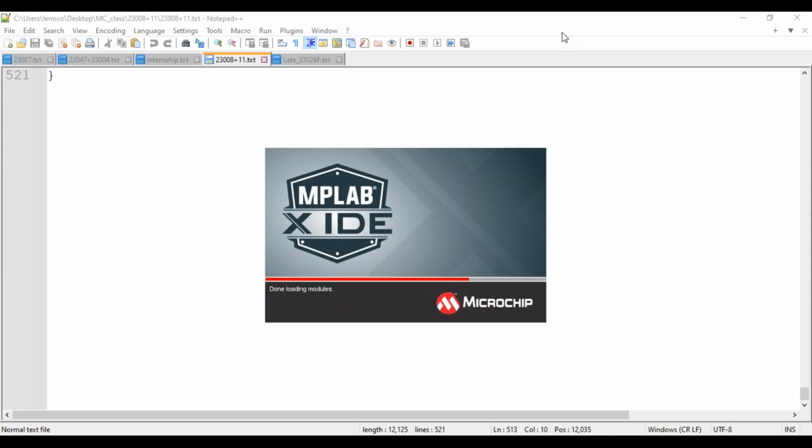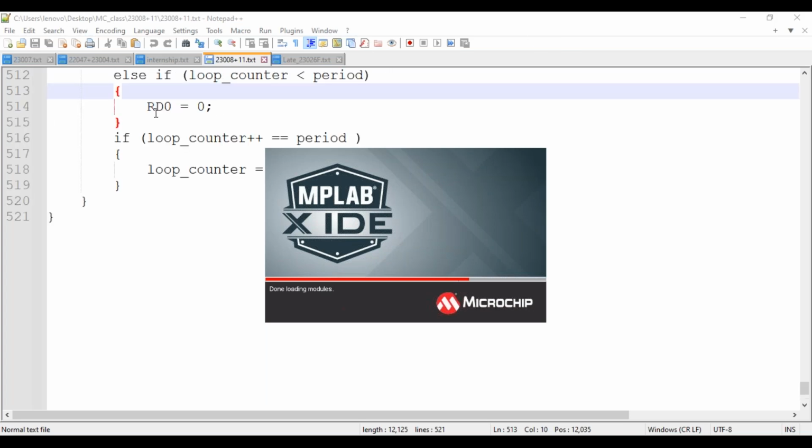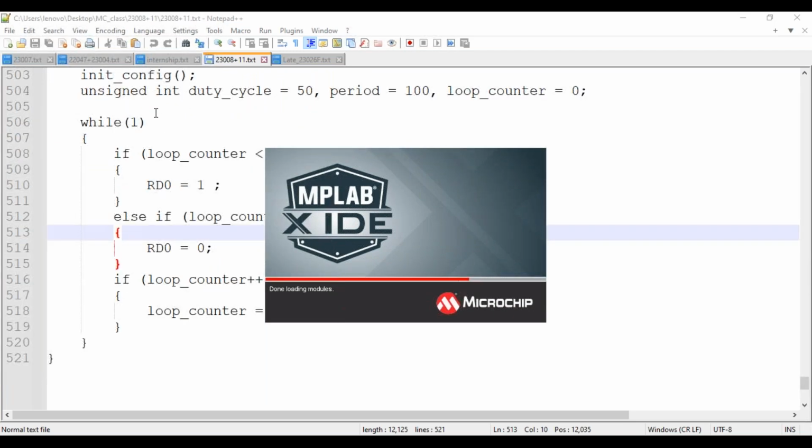When we configure the timer as a counter, we are going to make use of an external clock, that is, an event which occurs at the RA4 pin of the microcontroller. Upon identifying either the rising edge or the falling edge, whenever the corresponding edge is detected at the pin of the microcontroller, the tick is going to happen. And as usual, an interrupt gets generated after there is an overflow from 255 to 0.